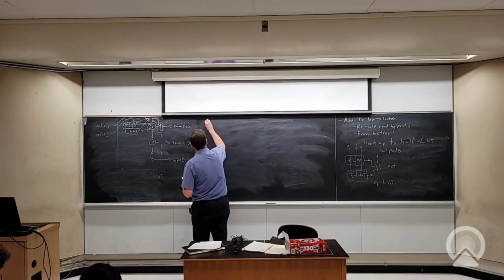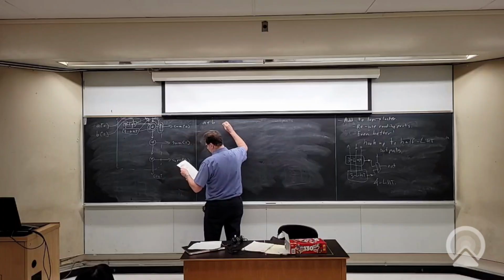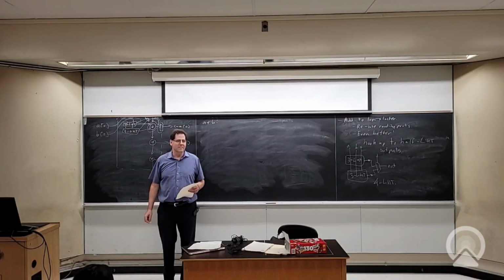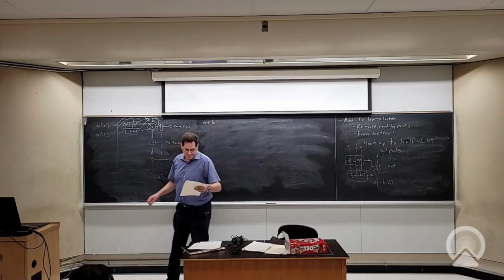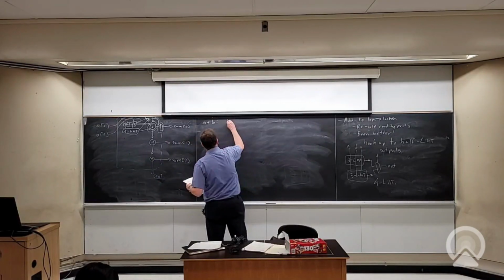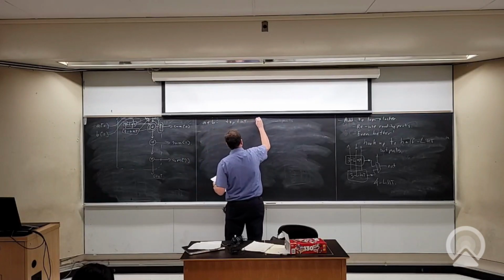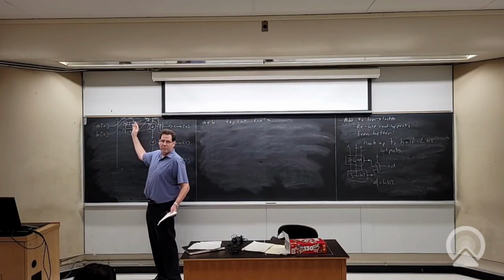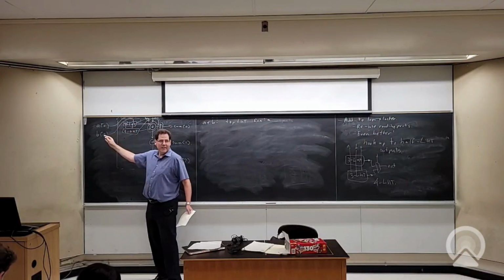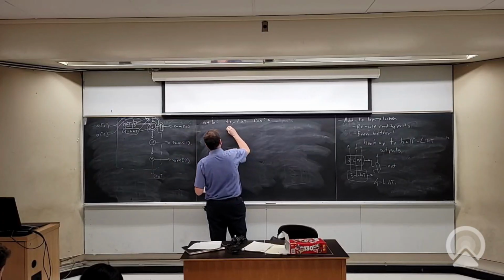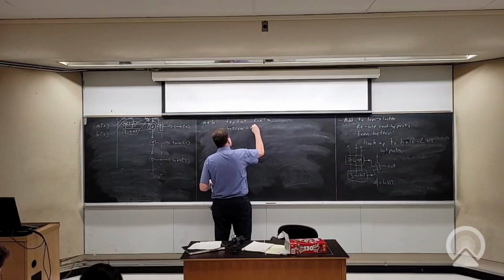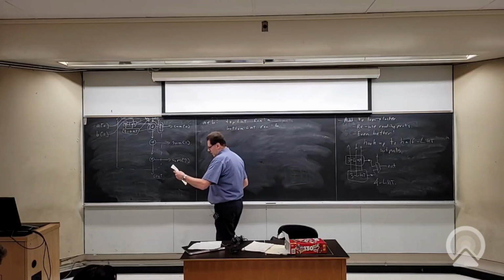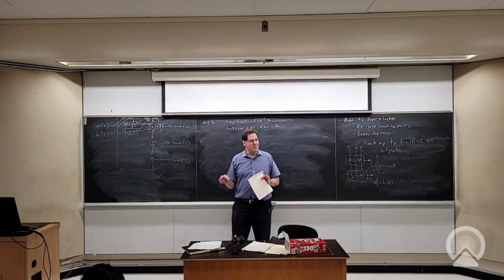Yeah, let's see how this works. Let's say I want to do A plus B, right? That was the first thing I did. So what do I put in these LUTs to do A plus B? This is like an easy question. Yeah, so the top LUT function is A. It's got three inputs, it ignores two of them, and it's just a function of A. It's just a pass through for A. The bottom LUT is B.